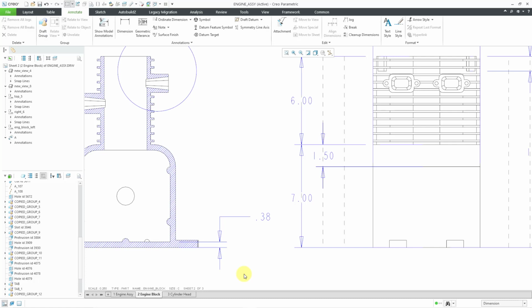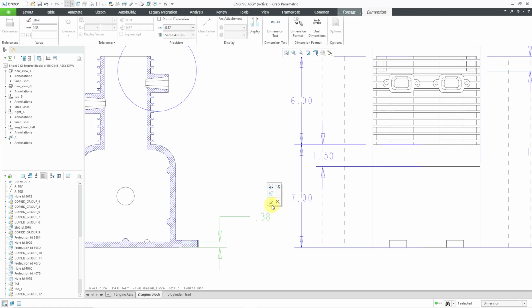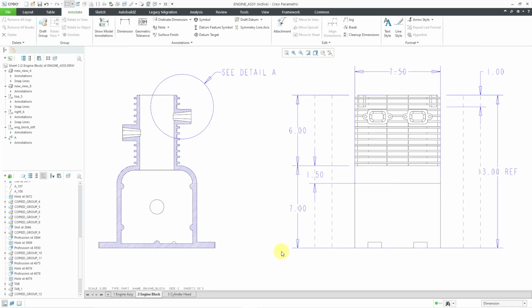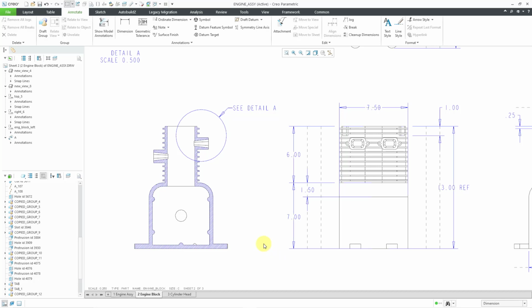There are a couple different ways of doing that. The first way is by using the erase command. If I click on a dimension, there's a little icon in the mini toolbar that looks like an eraser for a whiteboard. So I can click on that, and then it's still going to appear on the computer screen. This gives you a chance to say, oh wait, I actually didn't mean to erase it. I want to unerase it. But the next time that you click on the background of the screen, that dimension is going to be erased. And erase means that it's just temporarily removed from the view.